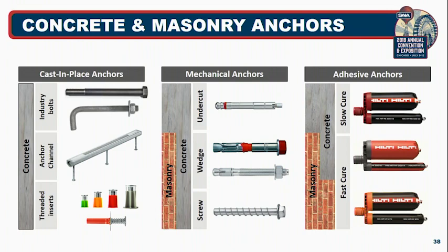Something else that's very, very critical when you're looking at adhesive anchor systems is hole cleaning. The presence of dust, debris, and such in the holes can tremendously affect the performance of adhesive anchor systems. So it is important, it's critical actually, to follow the manufacturer's printed installation instructions in cleaning out the holes with the prescribed number of wire brushing strokes. In fact, I have a slide that'll show you that, and using compressed air to blow out the dust to make sure that that hole is cleaned properly.